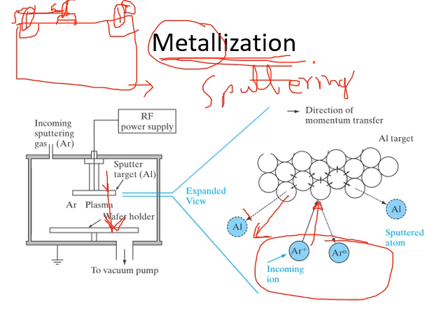So finally, we are bombarding the argon atoms, and because of that bombardment aluminums come outside and are pasted on the silicon wafers, right? It is pasted only where it is required, not throughout. I have drawn the arrows throughout, but it is pasted only where it is required, like on the gate, then on the source, and then on the drain.